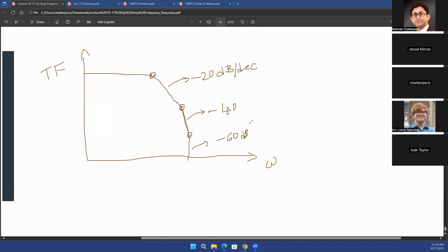So that's a great question. Generally, when you talk about cutoff frequency, you talk about the first pole, right? The cutoff frequency for this system is just the frequency of the first pole, which is over here. Let's call it P1. And then you have the second pole over here, which is P2. You have the third pole here, which is, let's say, P3, and so on.